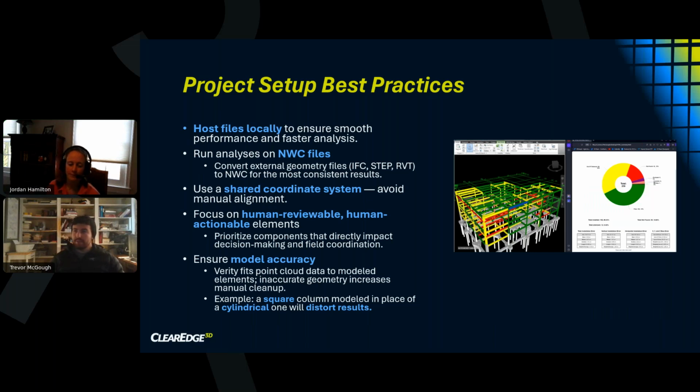Yeah, and I think this is a big one, putting a little time up front to organize and get things ready before bringing it over into Verity instead of just, say, chucking the whole MEP model in there. Because in addition to the pipe runs, we also might get these little inserts, might get a couple hundred of those, and those elements just don't have enough point cloud data on them anyways, and so Verity usually flags them as either not founds or uncertains.